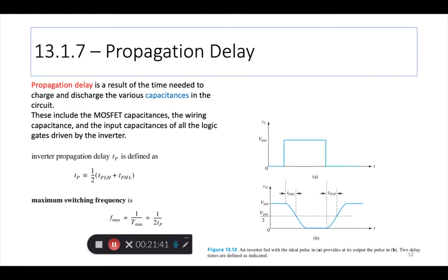So while we don't show capacitances so much, we just show the devices, NMOS, PMOS, and just show some resistances, we think that's the end of it. But we know that anytime there are two terminals, there's likely to be capacitance. Even small wires with respect to ground have capacitances. So a lot of stray capacitances, little values, but they're all around and they all need to be charged and discharged. And that process takes time. Those are RC time constants, right? So those times all add to the delay at which your circuit can work.